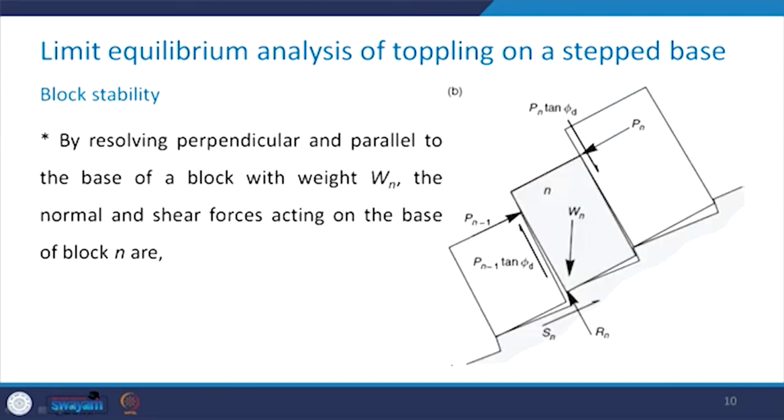Now, by resolving perpendicular and parallel to the base of a block with weight Wn, the normal and the shear force which will be acting at the base of the block can be obtained as Rn equal to Wn cos of psi p plus Pn minus Pn minus 1 tan of phi d, equation number 21.